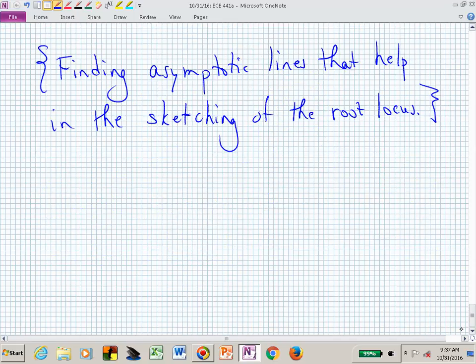And now let me give you 2 ways of sketching these root locus. These asymptotes. One is going to be the angles. So the angles might be at minus 180, or it might be plus and minus 90, or it might be plus 45, minus 45, plus 135, minus 135. Those might be our angles. And then we have to figure out where those asymptotes are located, where's their centroid on the real axis. Let me try to state those two properties, the angles and the centroid.